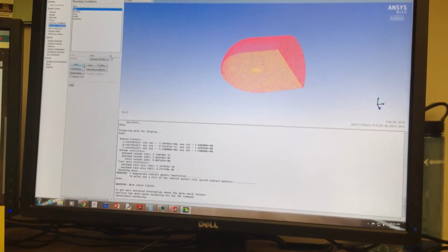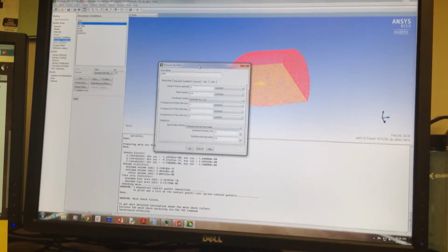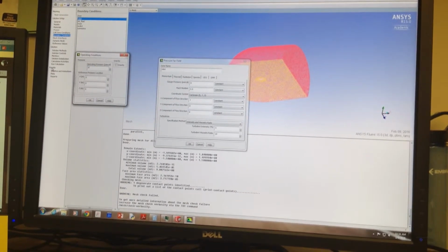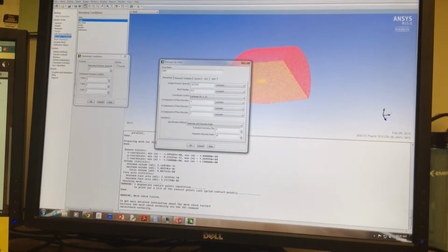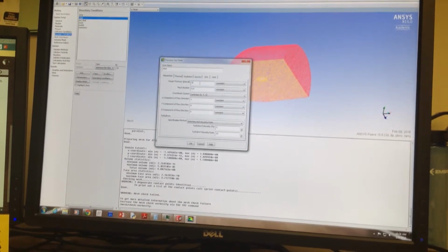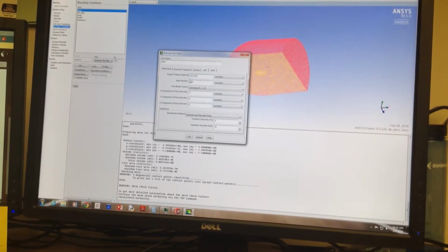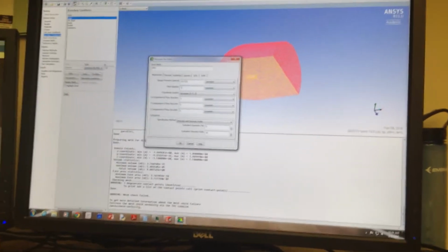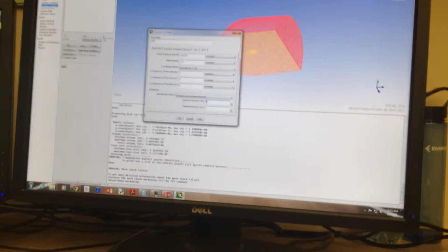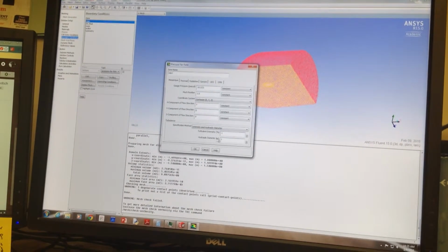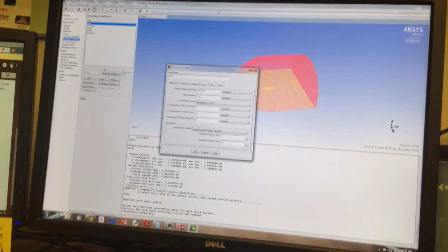And in inlet, pressure far field, edit, gauge pressure. In this case, just take off this and put 0 instead of that, because you don't have an I. Your Mach number: my first two are complex, and my last one's the real part. It's this column here. As long as we take this pressure far field boundary condition and we change that Mach number, then whatever.